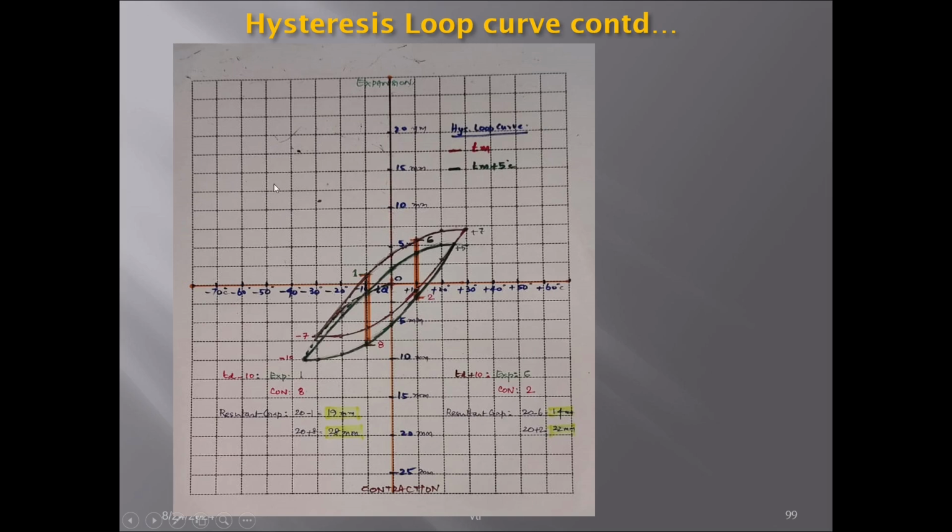Like that, if you take TD minus 10, the maximum expansion is 1 mm and the maximum contraction is 8 mm. Okay. So this is this one. So from there, how are we getting the resultant gap? 6 mm maximum gap is possible. In that case, when there is expansion, the gap will be reduced. With reference to one side, the reference line, our A gap is 20 mm. So 20 minus 6, because expansion reduces the gap, 14 mm will be there.